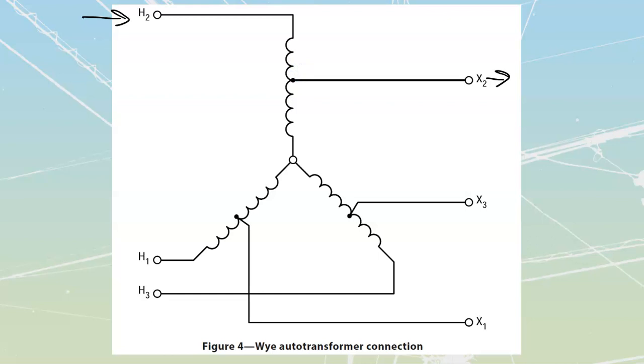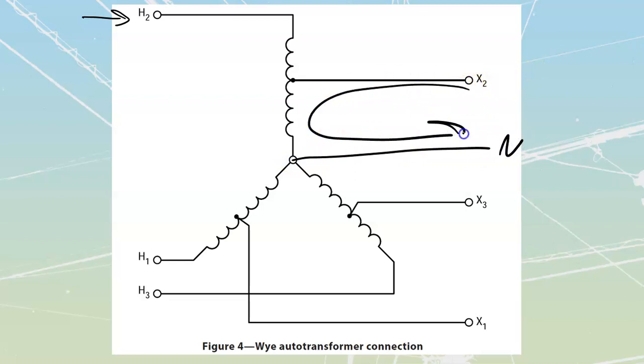We want to be really careful about what we use these Y autotransformers for. If you have a bunch of single phase loads, so if you connect this thing to a neutral over here, and you take a whole pile of single phase loads just out of this phase over here, we're going to have a lot of current. And if I get a lot of current, the current is going to travel through these windings, which are physical. They're made out of copper, which means that they have resistance, which means that I've now got I and R, and I times R is equal to V, or volts. So because we've got a large amount of single phase load going through that one, we would start to get a voltage drop across here.